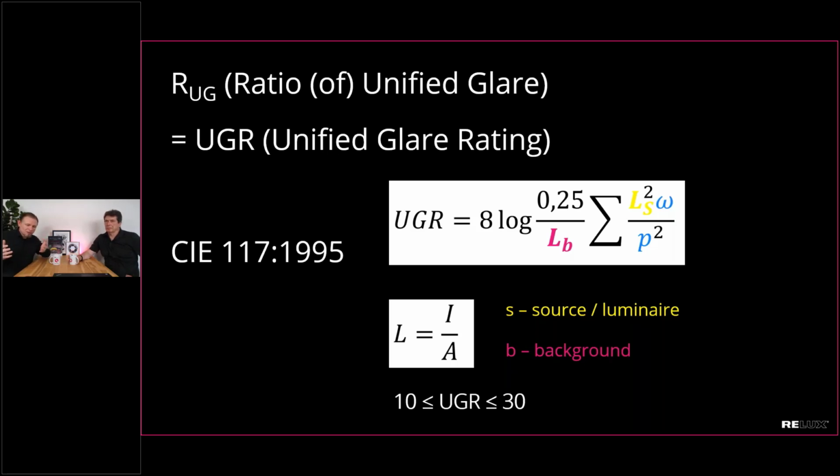So this is glare. Glare is nothing else than contrast, a difference between an active part and the background part. Nothing more. And this is crystal clear if you think about it. So glare is just high contrast. If everything is quite bright, then you have no glare. Of course, you adapt just to another level, and everything is the same ratio. Glare comes into place if we have a difference of luminances in our scene.